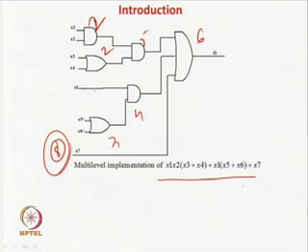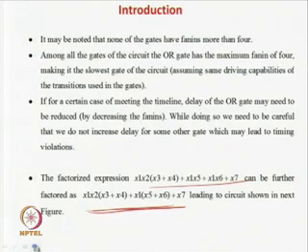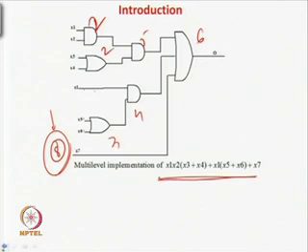If you keep on factorizing, you will find that the number of fan-ins in the inputs is decreasing, and also none of the gates have more than a certain number of fan-ins, like 4 in this case, that is the thumb rule. But in more formal terms, what are we trying to achieve? We are trying to achieve a minimal representation of this function. This is your function, and you are trying to represent it in a minimal multiple level format. So, when do you say it is a minimized representation?